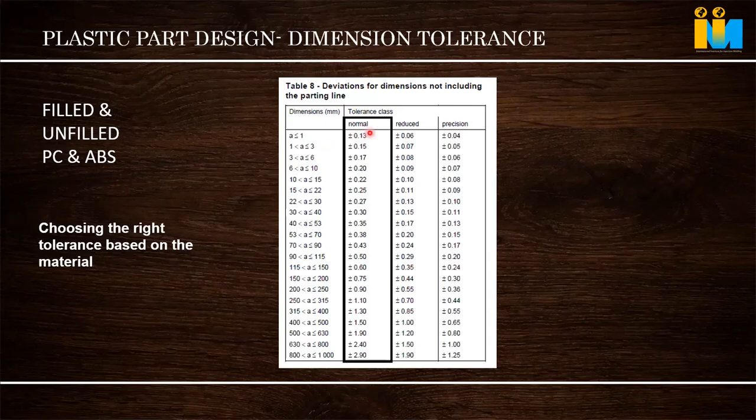There are three types of tolerance in any product design. One is the precision tolerance. Precision means you are giving a dimension so critically that it is very difficult to meet in production. Sometimes it will be over-defining the product. In a critical product like an MCB or aerospace, some application where there is movement, there will be one or two precision dimensions, and the second will be a reduced one. We are giving a higher tolerance. It is a little better to machine it and maintain it in the tool also for repeatability. We'll get better stability in the molding also. Third is a nominal tolerance.